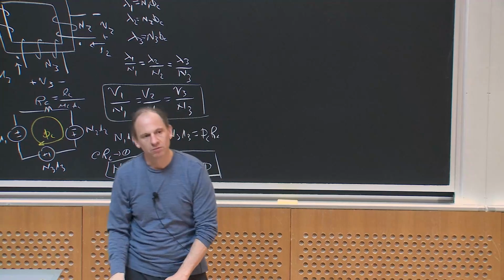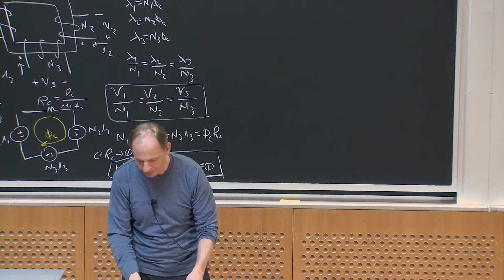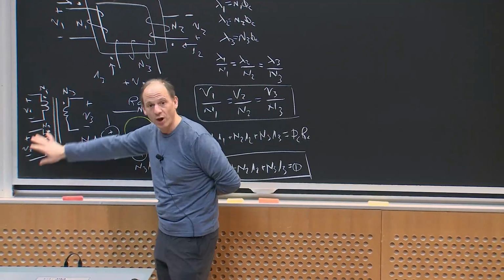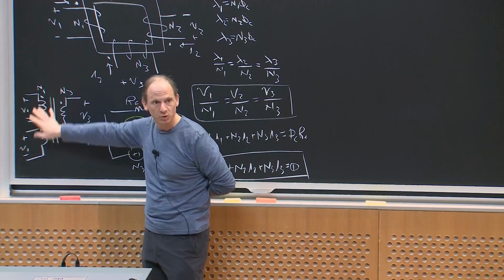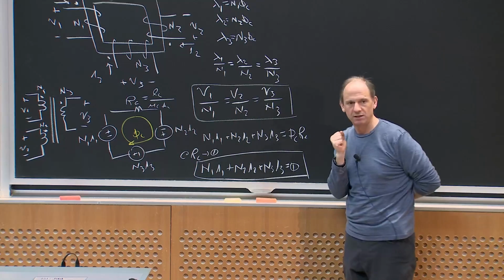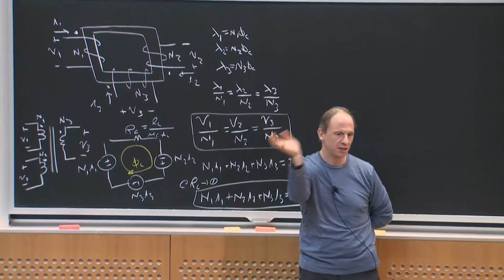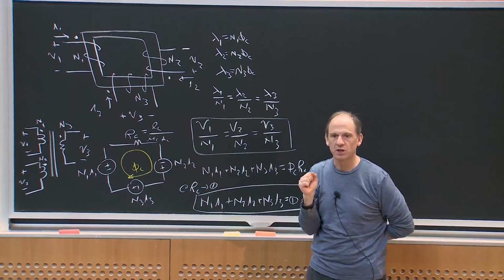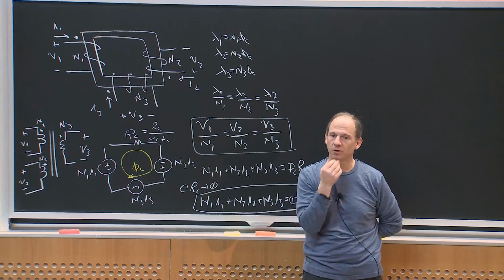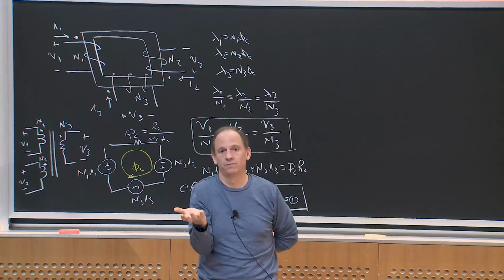So let's think about other possibilities, however. Okay. This is perhaps the most common way to build a 3-winding or 5-winding or whatever transformer. Where what we're going to get is a bunch of voltages at the terminals that are ideally ratiometrically related, because that's the most common thing we want. We'll see next week cases where we might want to do that for converter design purposes. Okay? But it's not the only thing you could do.